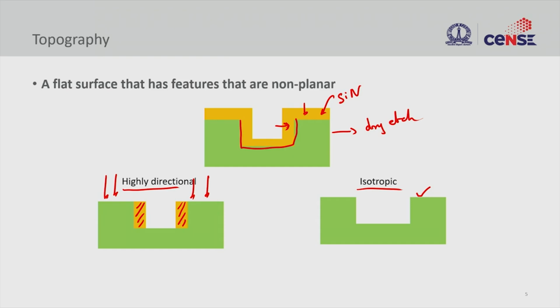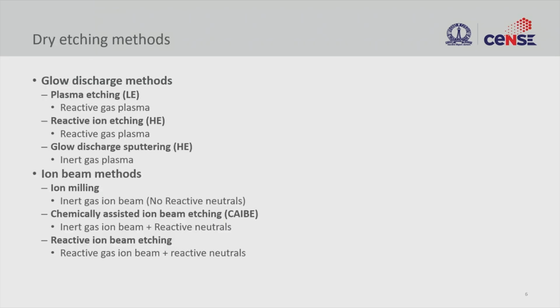The reason for that is it gives a uniform thickness. So when the deposition happens all over the place, this is the thickness I have here, but in this case it is T plus capital T, let's say. While I remove this thickness here, the remaining thickness is left on the side wall. So this is how you end up with a side wall coated film.